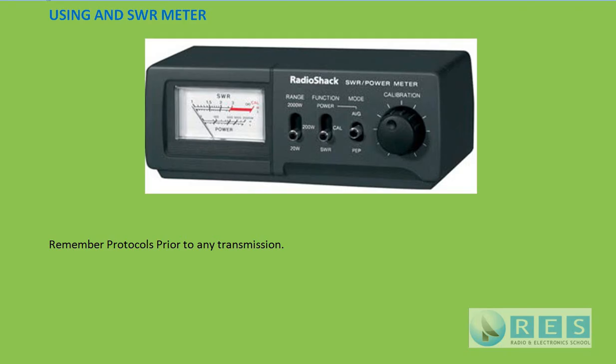So we need to measure SWR to be able to determine the match between the antenna and the transmitter, which is nominally 50 ohms. If the SWR is very high, it means that we're going to have extra losses in our antenna system, or there could even be a fault in our antenna system. So it's very much to our advantage to know what the SWR of our antenna is.